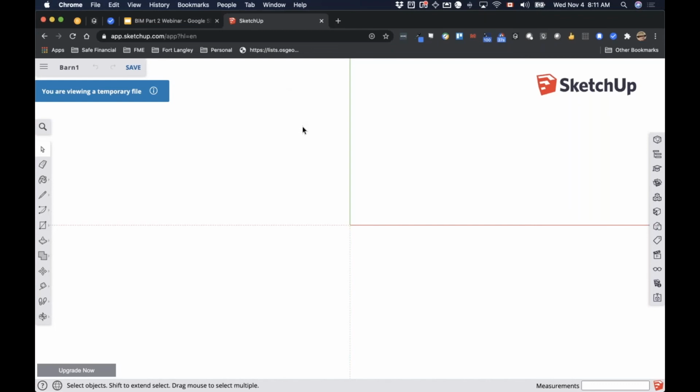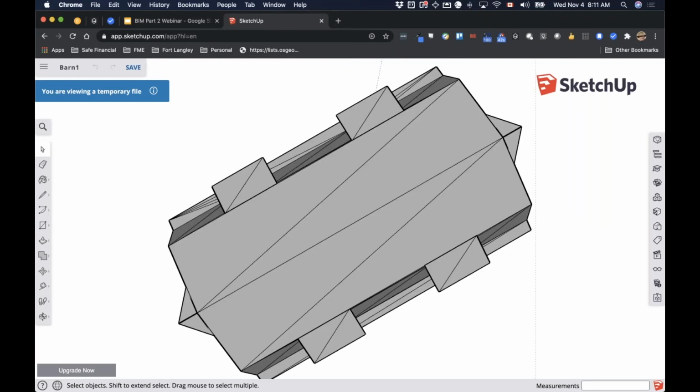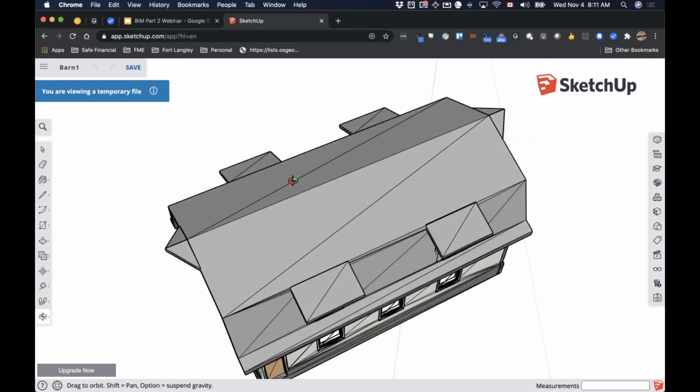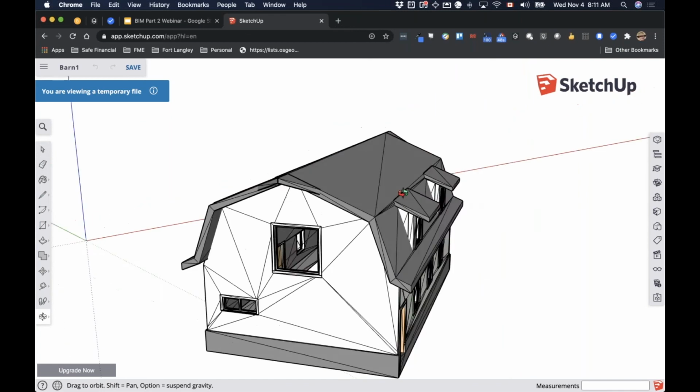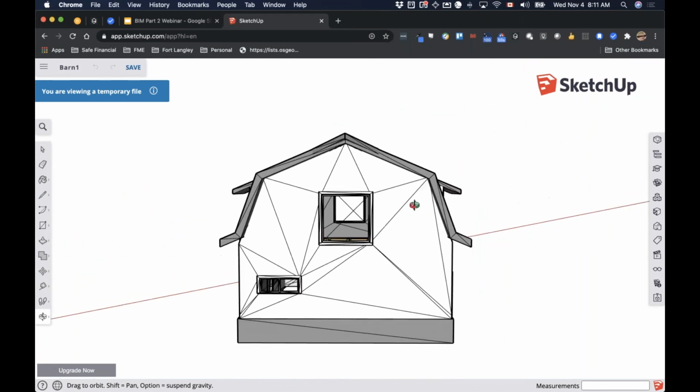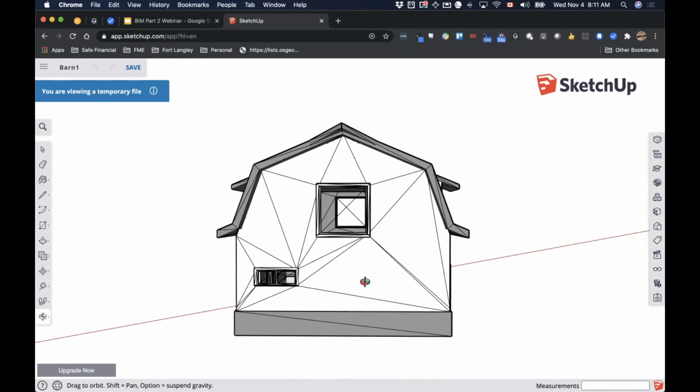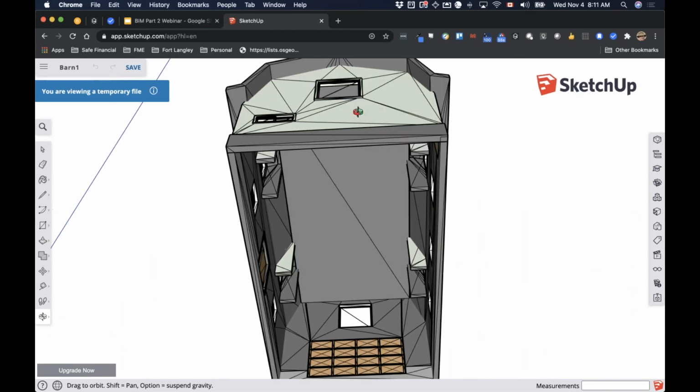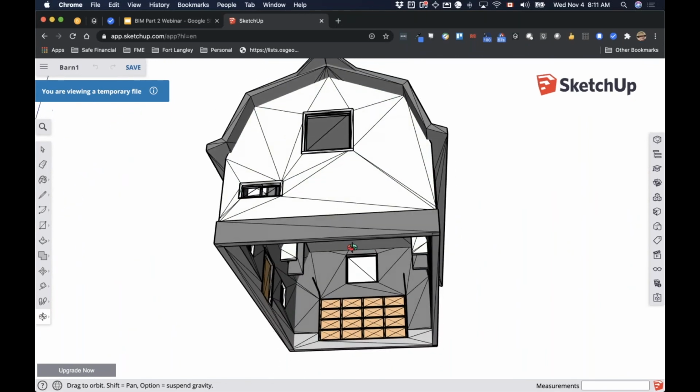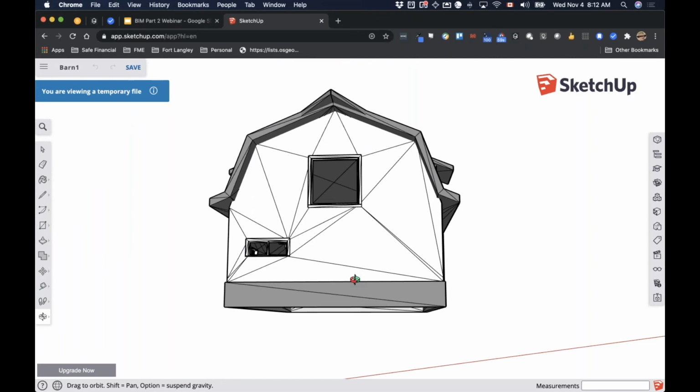And I get in here, and of course I can't see anything. So for the folks at home, typing Shift-Z brings you into here, and typing the letter O gets you into orbit mode. And we can tip it up, and here's the thing. Boy, it looks fairly barren inside there. I can see right through the other side. If I tip it all the way up and look inside the box, there's nothing there. So I did succeed in getting the empty shell.